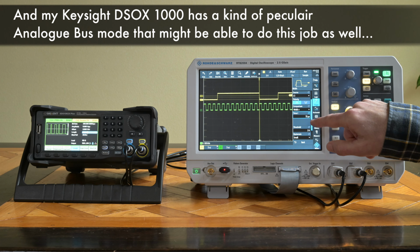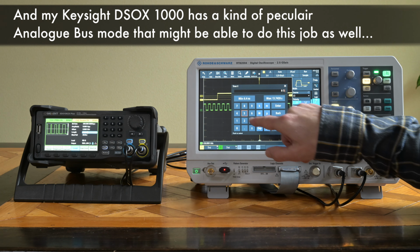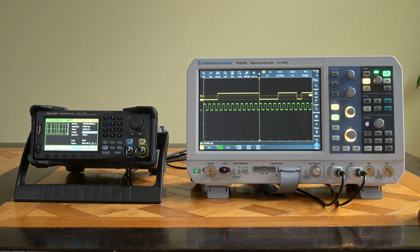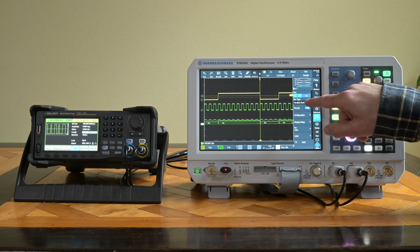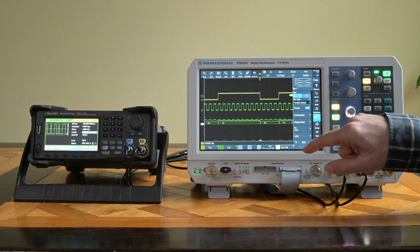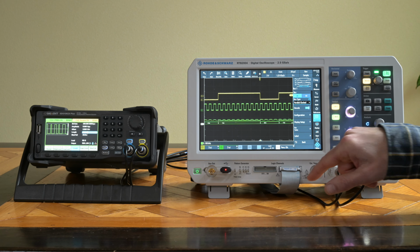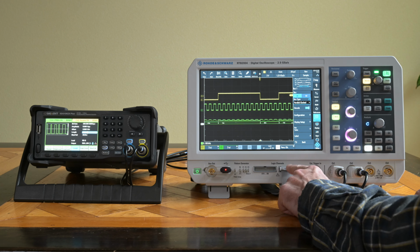Let's go back here to properly pick up the sync signal for the positive one. We're there yet. And then we have to select the parallel decoder, and it's here in the list of decoders. We have a parallel decoder and a parallel clock decoder, and the parallel clock decoder is the one that we're going to use here. But in order to do that, we will need the digital logic channel interface here.